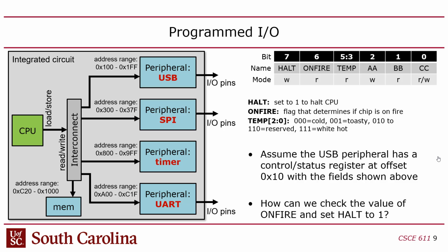Still going to be too hard, though, because even then, you have to stop it in the debugger and interpret a hexadecimal number as bit fields. The problem is that these bit fields are not always on multiples of 4 bits, and hexadecimal is a 4-bit multiple system, right? So if you need to find bit 7, you can't get that from the hex. You have to convert all the hex to binary by hand to figure out what bit 7 is.